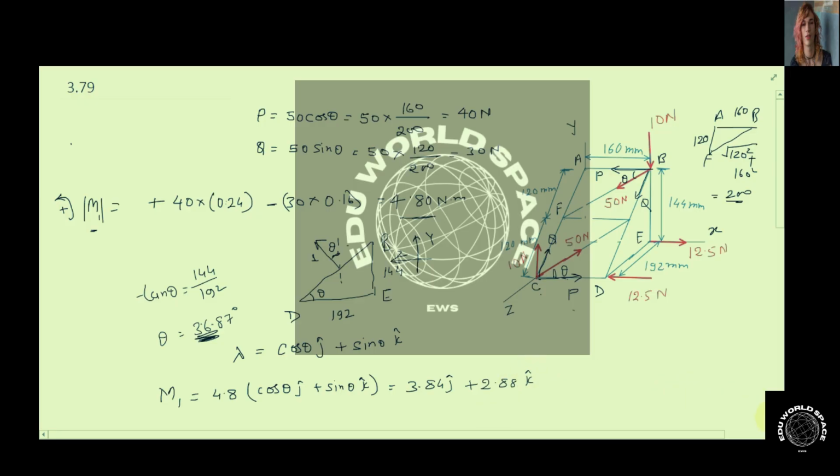So we have got the value of M1. Now let's say that moment vector, because of these two forces, is M2. Because they are of same magnitude and opposite in direction, one can observe that they will cause a clockwise couple if viewed from the top of the plane XZ. So their couple will be in negative y direction.